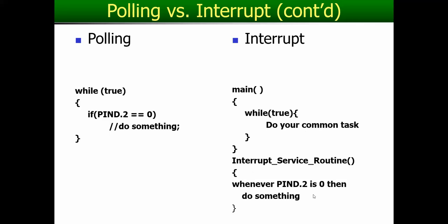But if you look here, whenever that pin goes low, we are automatically interrupted. We leave this loop and go and execute the interrupt service routine. This is a new term that you are seeing, interrupt service routine, or ISR for short. It's a piece of code, a function that we write, which is executed by the CPU every time an interrupt occurs.